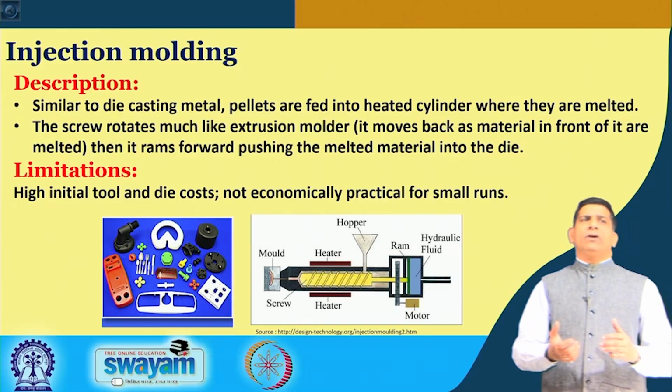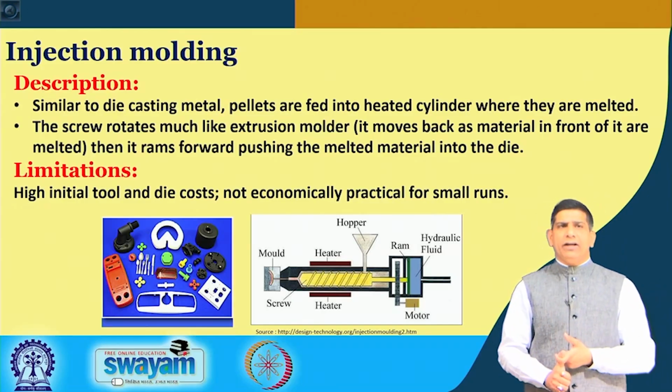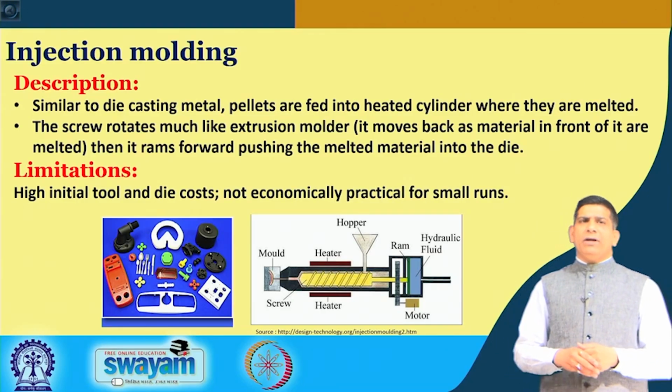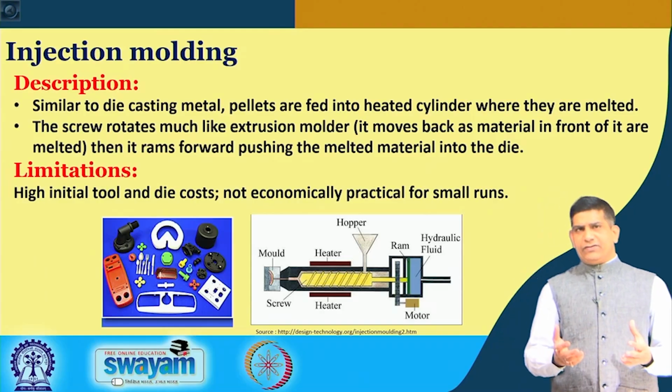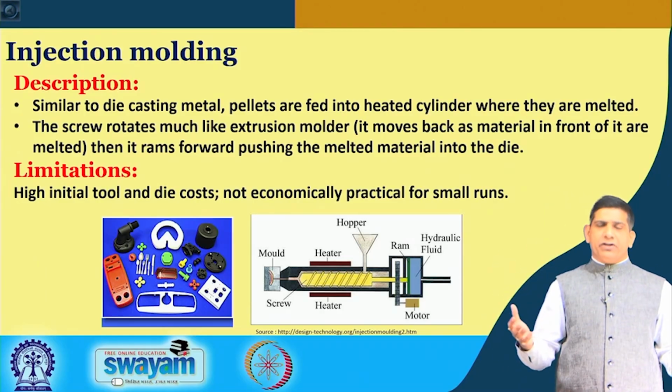So again, what is the limitation for that? High initial tool and die cost, so it's not economically practical for a small run. You need to do massive production of this.